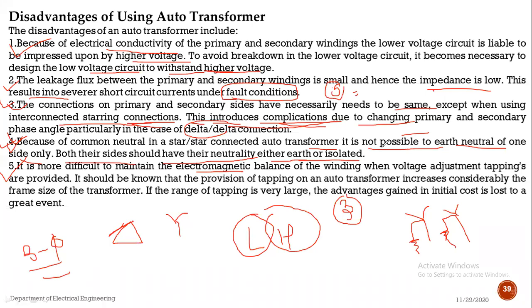It should be known that the provision of tapping on an auto transformer considerably increases the frame size of the transformer, meaning the size of the frame, yoke or core will increase.